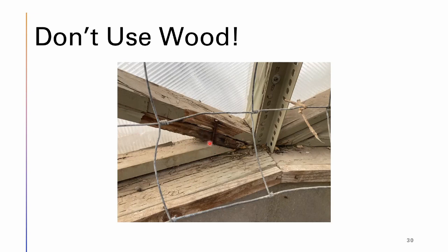Look at that. What happens is you have so much humidity in your greenhouse. And once again, recall what I said before about that relative humidity. When the air cools, it condenses on your glazing, and then it freezes overnight. When the sun hits your glazing, it melts. And guess where it runs onto? It runs onto your wood. So every morning, this wood would get saturated by water.